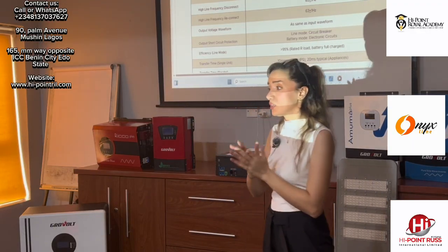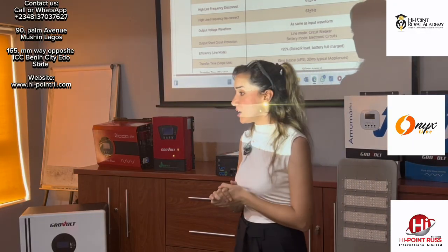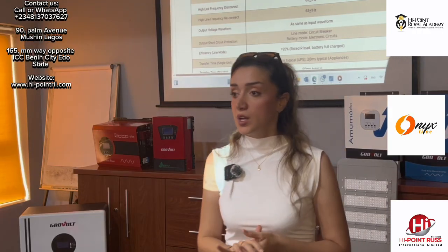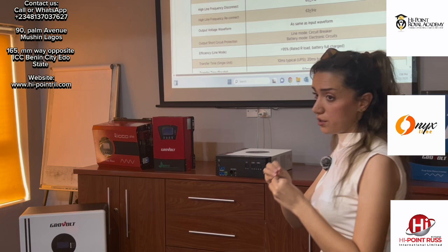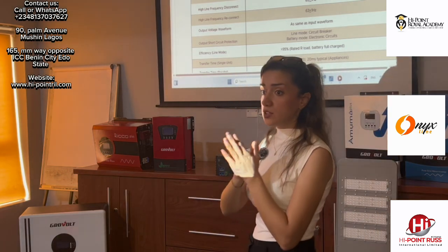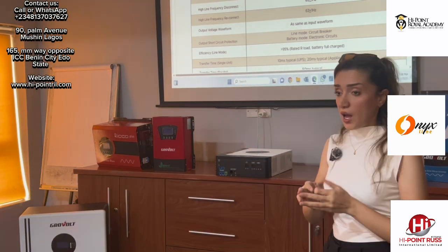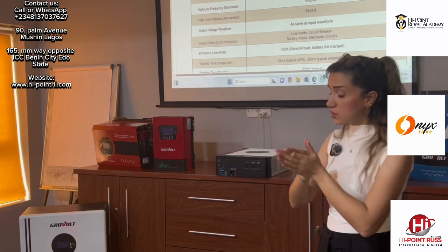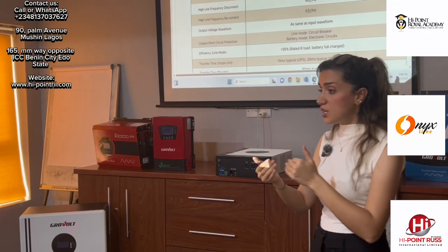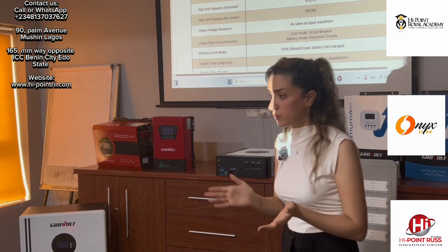So this one is not allowed to have blinking in the power. So we have to see in our inverter how much the transfer time is, and check how much transfer time your machine needs so that it doesn't blink.